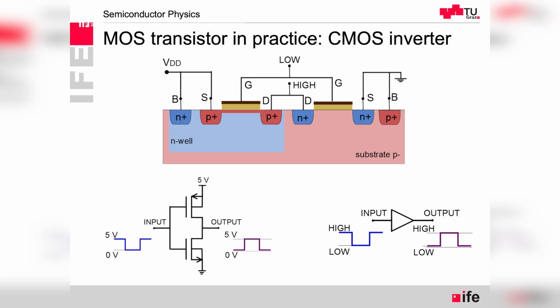With the on resistance and the capacitance, we can determine the rise and fall time of each individual block. In practice, such structures are used with, for example, current starving or a charge pump regulating the power supply, because we really want the frequency to be stable with the operating conditions.